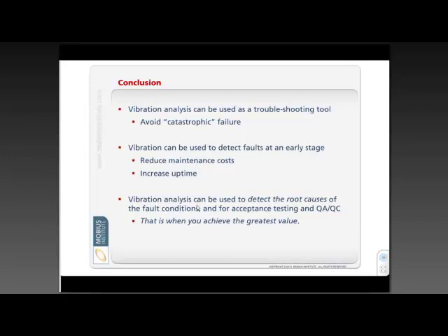But if we can use it to detect the root causes like unbalance and misalignment and lubrication problems and so on, and do something about it, if we can use it for acceptance testing and as a sort of quality control tool, if you like, when bearings are installed or machines are aligned, check it then, make sure the job's done properly, use it as a supporting tool, and then the machine will run smoothly and we'll detect fewer